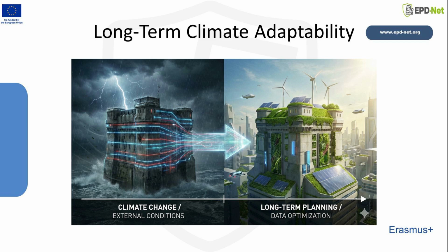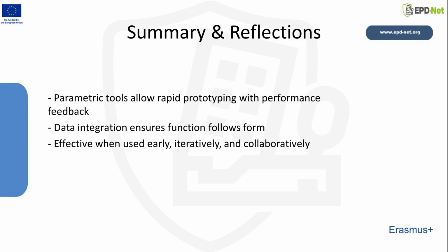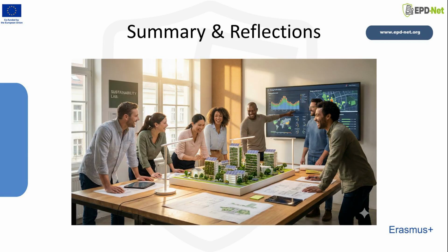The application of parametric design to climate-responsive architecture fundamentally aims to optimize buildings for energy efficiency and environmental compatibility by automating complex evaluation processes. Parametric tools allow rapid prototyping with performance feedback by enabling designers to simultaneously evaluate a wide range of alternative solutions and use quick analyses for real-time design decisions. This capability is achieved by linking parametrically controlled geometry to energy simulation tools and optimization algorithms.